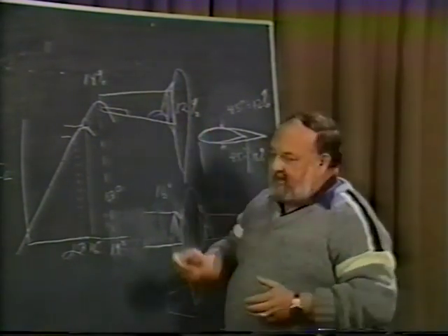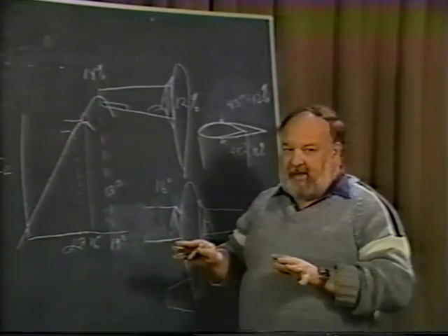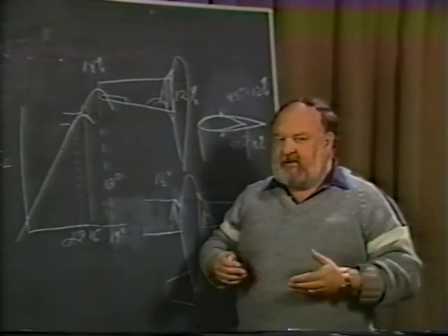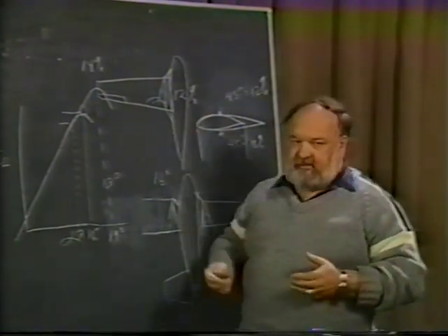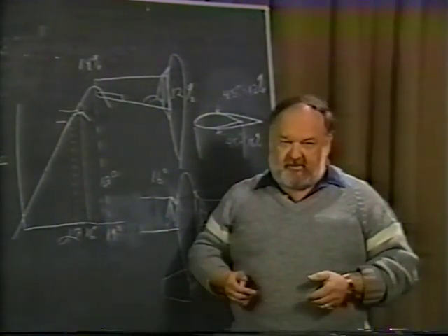One side effect of all of this is how does the airplane act in a spin? I mean, first we're talking about stall patterns, but then what happens once you really get into a spin? Well, most of the time the same things that give you good stall characteristics and good stall patterns will be the same things that give you good spinning characteristics also.